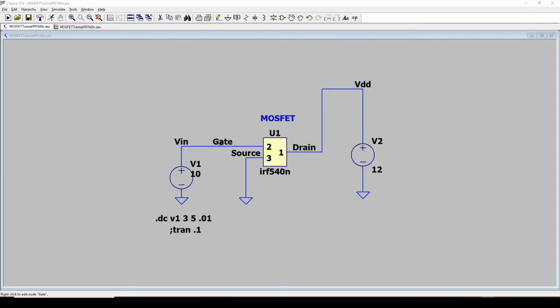As I increase this gate voltage above about 2 to 4 volts, this is going to turn on. We're expecting that once it's on, there's going to be very little change in gate voltage needed to make it go totally on, which means you have the maximum current flow. It's probably only varying this gate voltage by a volt or two, and we're going to see that. So that's where we stand with our basic setup. Now we're going to start varying these things and do a simulation to see what the results are.